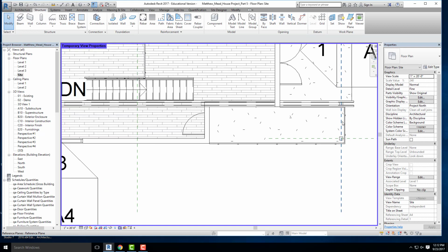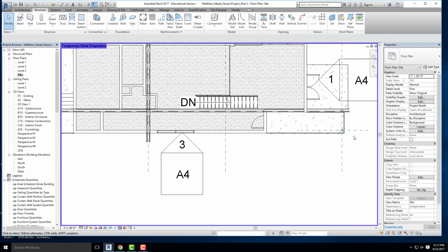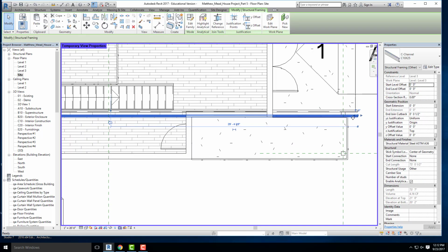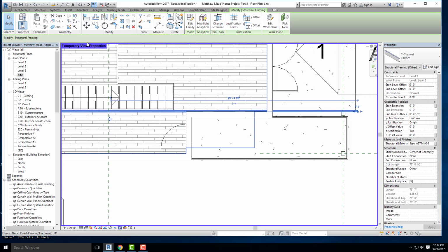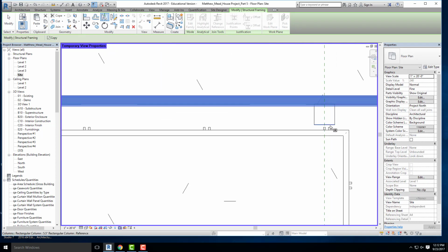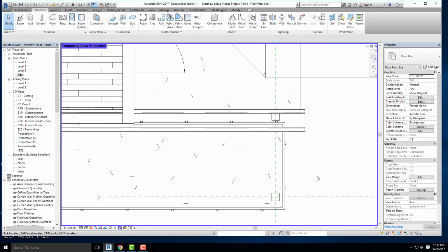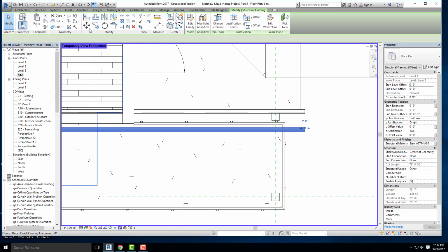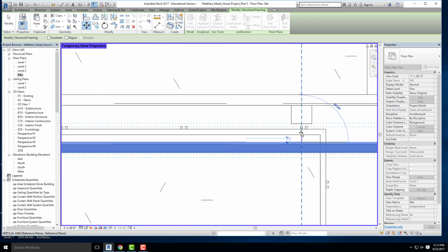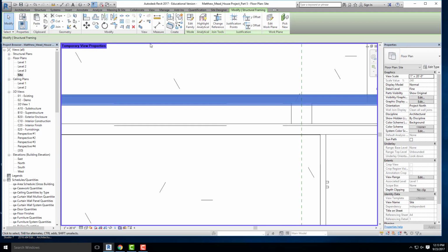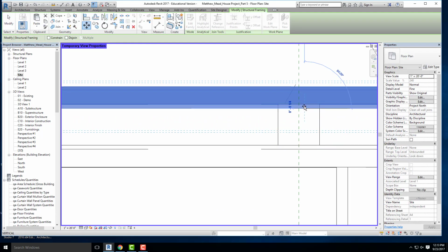So I'm going to draw that axis, and it will mirror it over to the other side of that column. What if we pick the edge of the column, the other edge of the column? You could, but technically you want to mirror it over the center of the column. So that won't work. Because if you mirror it over the edge, watch, let's just try it. If I click on that beam, and I click on mirror, and yes, you could select the edge of that beam, but notice that it's way over there. So if you really wanted to, you could move it, but you could be a little bit more efficient with that. Okay?